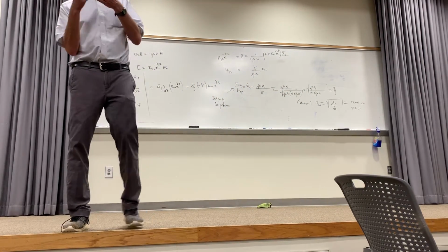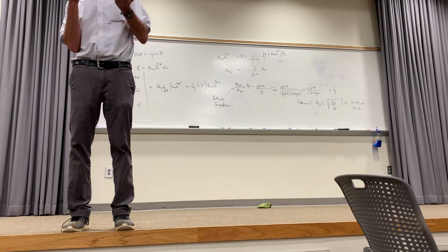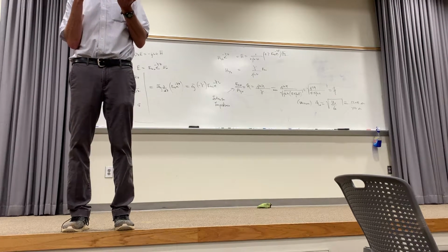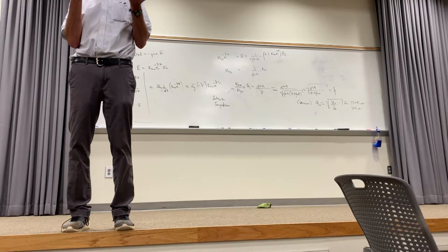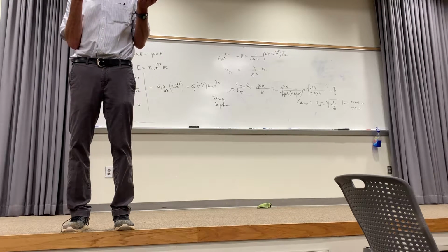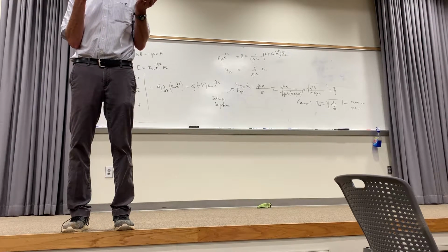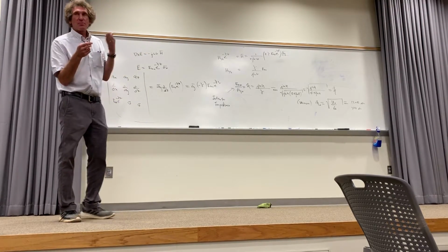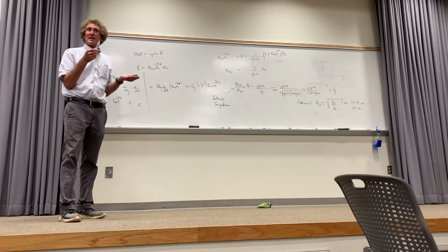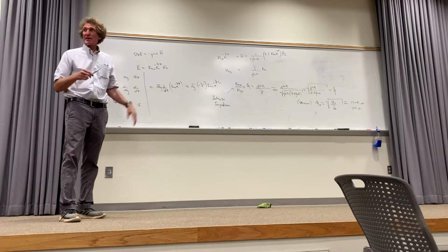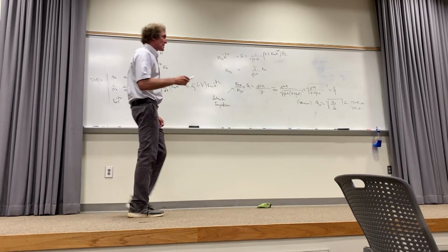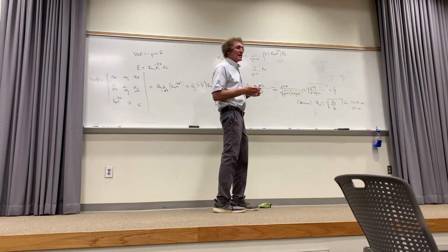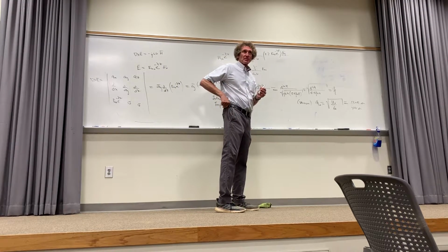This is why it's so important. If I measure an E field of 5 volts per meter, I know the H field associated with that is going to be 5 volts per meter over 120 pi. I know that ratio, which means I know what the H field is. If I have a magnetic probe, called a B dot probe, and I multiply by mu naught, that's what the probe would tell me exists. It's called the intrinsic impedance of free space.